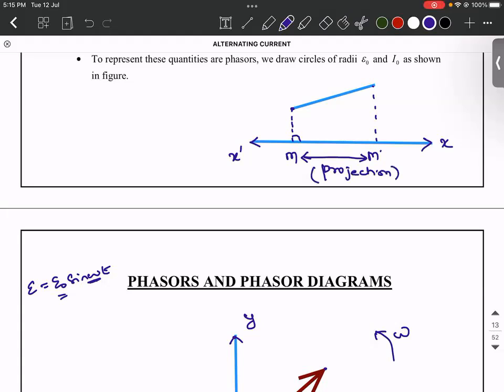You learn about this in detail in a chapter named three-dimensional geometry in your mathematics. So now you are able to understand what projection is. They might not give this exact definition, they would have given you a formula, but you have to visualize what projection is. It is the distance between the feet of the perpendiculars drawn from the ends of a line segment onto a line. Projection basically means dropping perpendiculars. So this length is called the projection of this line segment L on L dash.